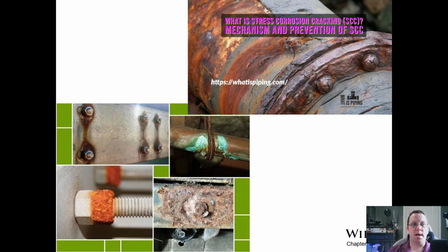When you have selective corrosion, you have things more like what's on the left side here. So different versions of galvanic corrosion. So things between where we have a couple bolts and nuts and maybe a washer with a slightly different material. Those different grades of steel, different carbon contents being uncoated, not being a galvanized washer or something. So even if this part of the frame is some sort of a zinc coated steel, the washers themselves being an uncoated steel is enough to have created this, with the presence of water.